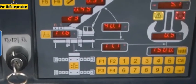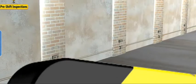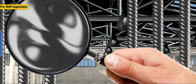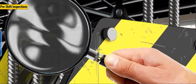Keep the control station clean and make sure all labels and warning signs are legible. All machine guards should be in place and undamaged. When checking the cables, look for kinks, crushed spots, and broken threads or sections. Also look for unwinding in the wire rope and separation from the rope core, also known as bird caging.